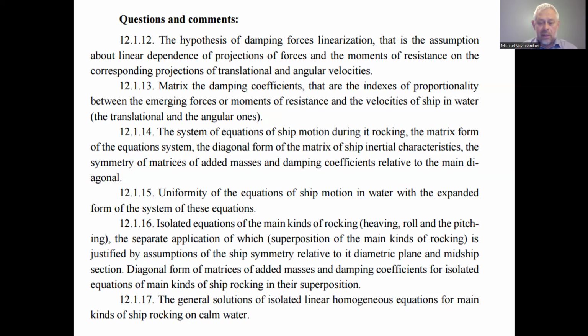perhaps we remember, in the forces method used for determination of displacements or for decision of statically indeterminate mechanical systems. In this method, we use the canonical equations, and for the canonical equations, we had the factors, and the factors are the unit displacements, the displacements in the definite absent connections when we make the main system out of the assigned statically indeterminate system.